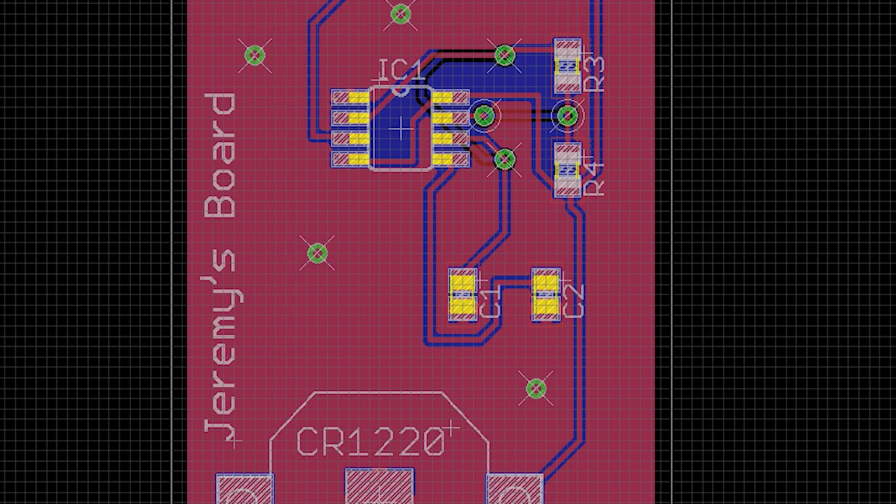At that point, you would want to output the actual solder layer as well that specifies the solder paste layer that specifies where paste would go down from an automatic paste machine so that then a pick and place machine could automatically place parts appropriately. And that adds an additional layer of complexity as well that I won't dive into in this video. But that's basically the gist of it.